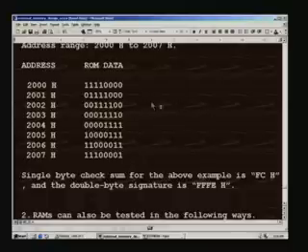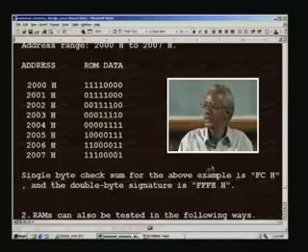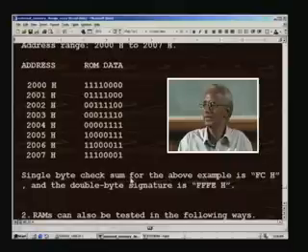So, keep the result and add repetitively the subsequent bytes. For example, that result you add with this one, once again ignore the carry and keep repeating till you have exhausted all the data, and finally you will get a 1 byte answer, and expressed in hexadecimal is the checksum. It is also known as the signature, and you can also have a double byte signature.